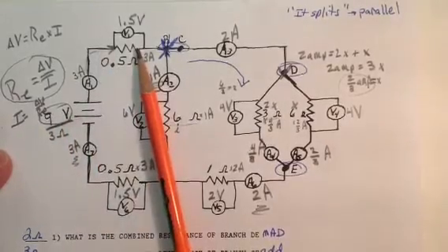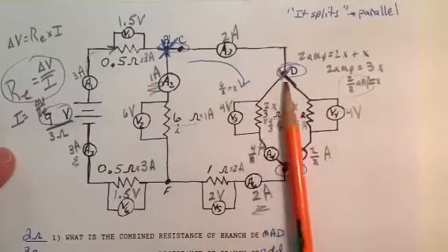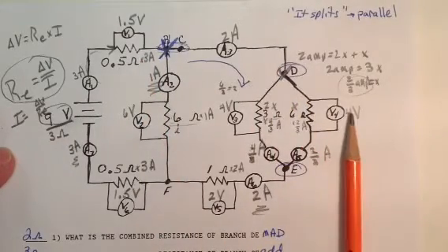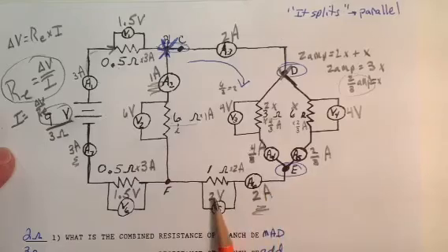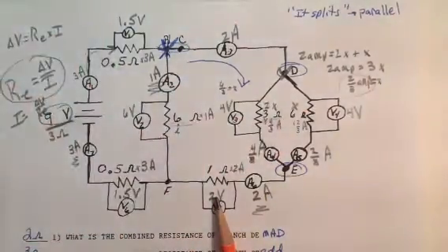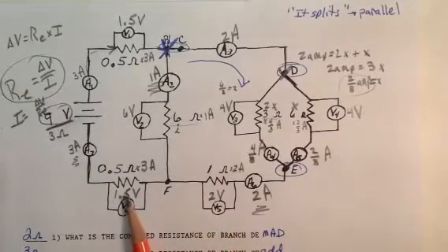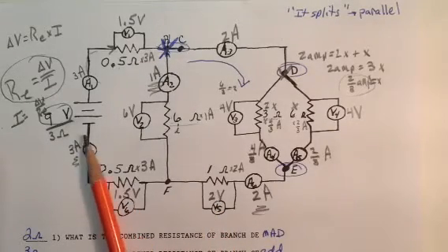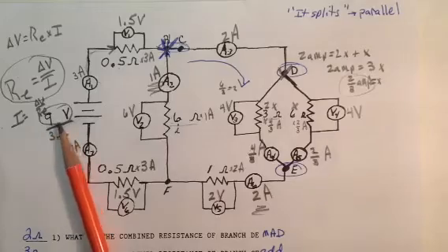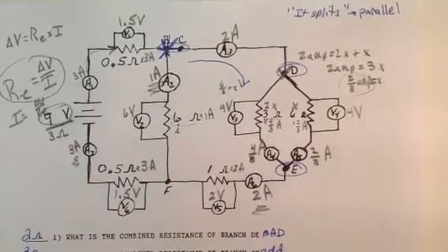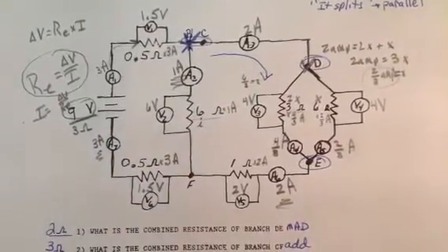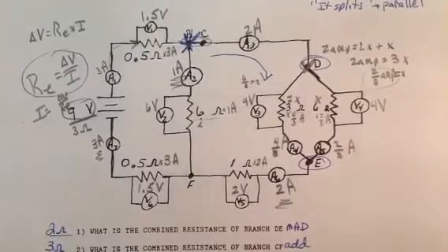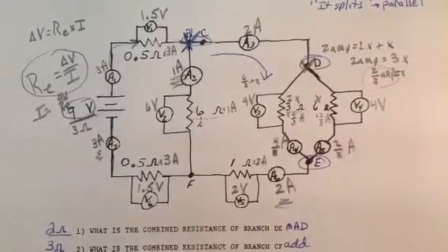Work out to the third path, 1.5 volts. I run across this one, 4 volts. Keep coming, run across 2 volts. If I add those 3 together, I get 7.5 volts. Finally, run into this one again. 7.5 plus 1.5 is 9 volts. Each path gets the same voltage, which is what should happen in this circuit.